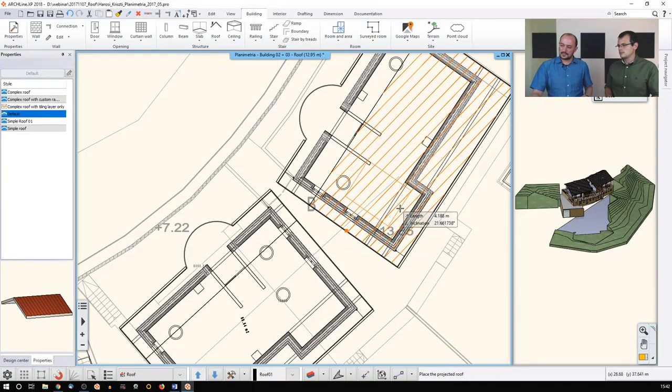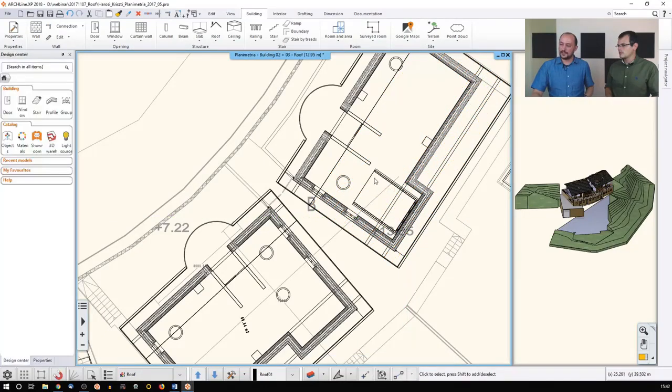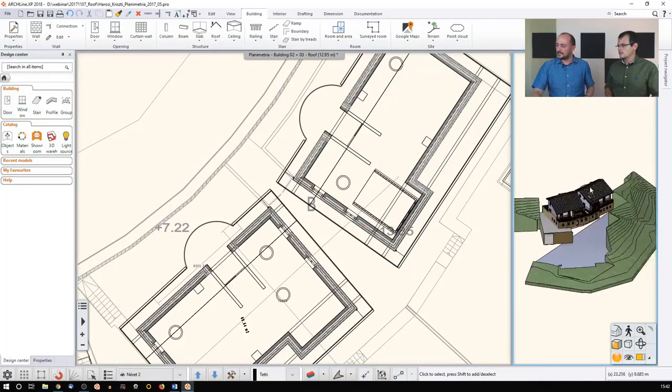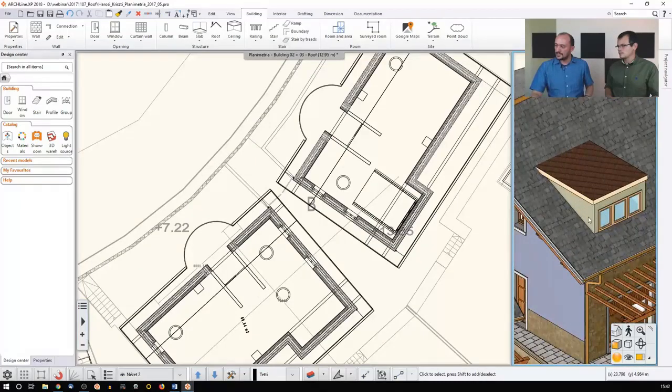Now the software understands that, okay, this is the roof plane, and I'm able to position it somewhere. And let's say I'm about to put it here. So the software creates the walls, the roof, and everything else, and now it's there. So this complex shape, which would otherwise be a bit difficult to draft, is set down to properties: the thickness of the wall, number of windows, pitch of the roof shape, and actually the shape of this roof.